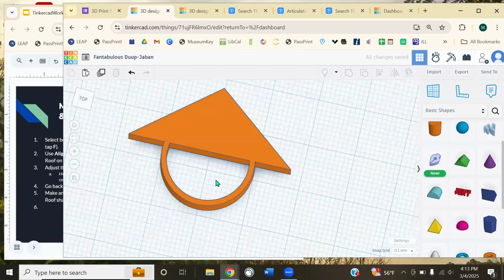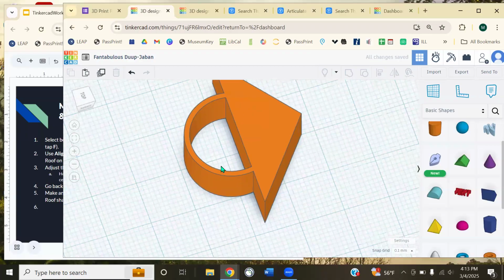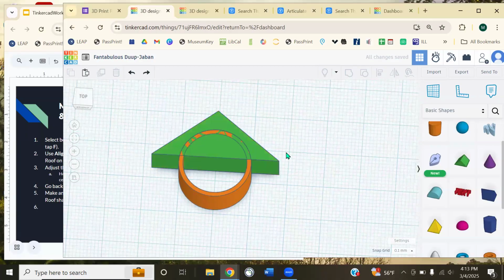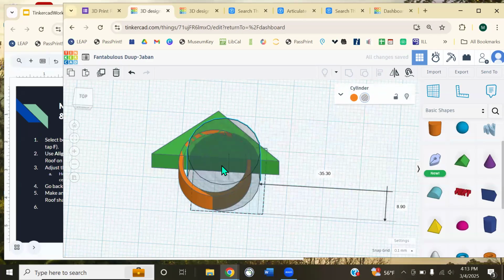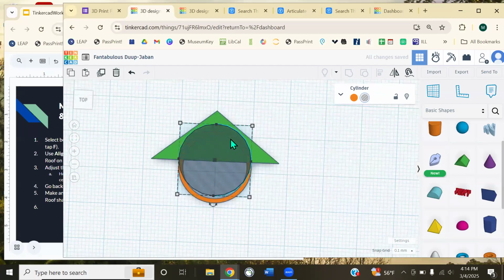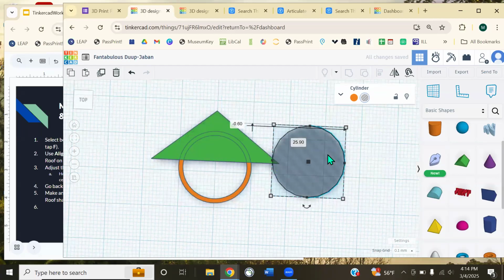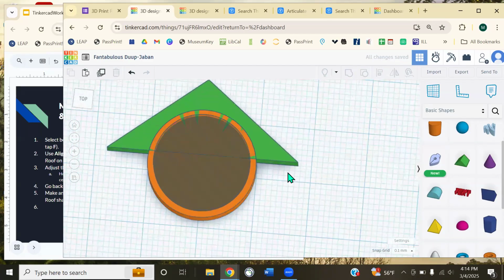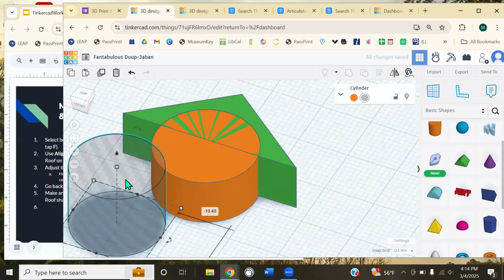But you can see when I do that, I still have the inside bit of the thumb ring. I can undo that. And then what we can do now, instead of making a second hollow object, sticking it back inside and recutting that out, is click on my ring. I'm going to ungroup it. Now I have my 3 objects back again.